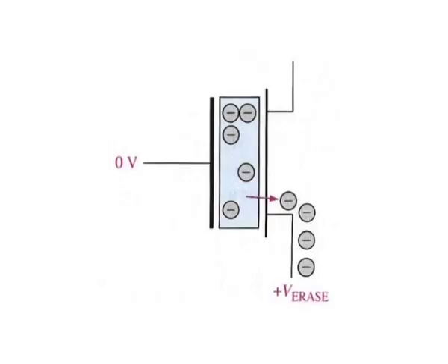Erase. During an erase operation, charge is removed from all the memory cells. A sufficient positive voltage is applied to the transistor source with respect to the control gate. This is opposite in polarity to that used in programming. This voltage attracts electrons from the floating gate and depletes it of charge as illustrated in figure. A flash memory is always erased prior to being reprogrammed.